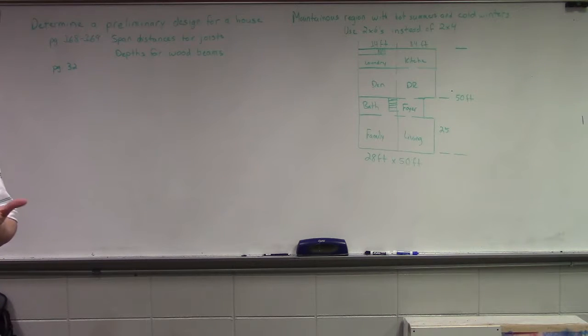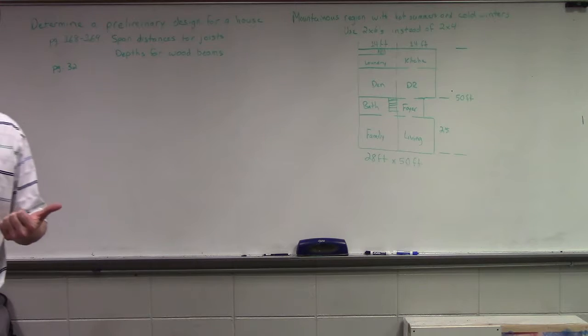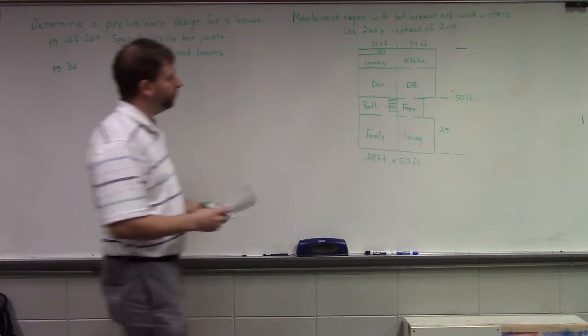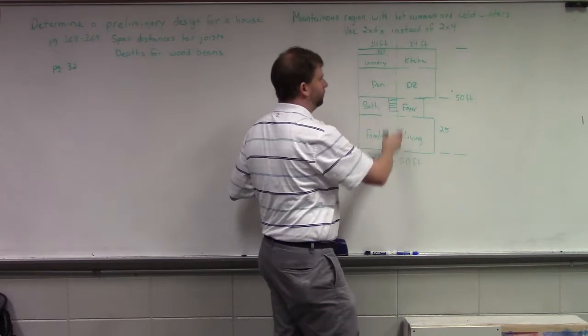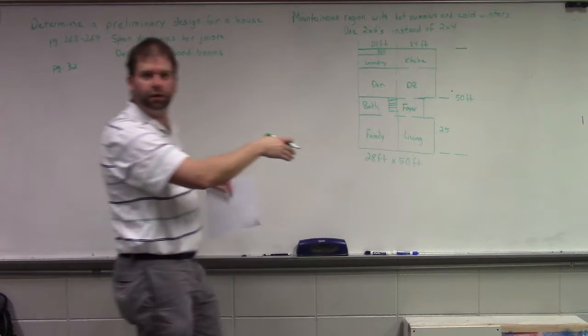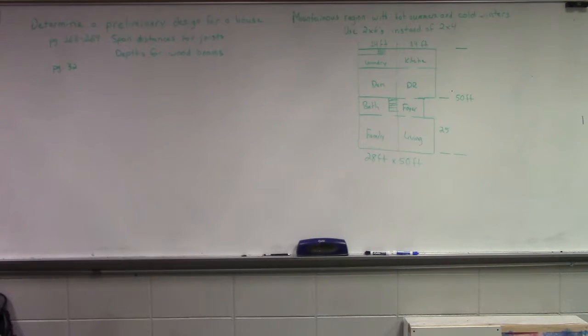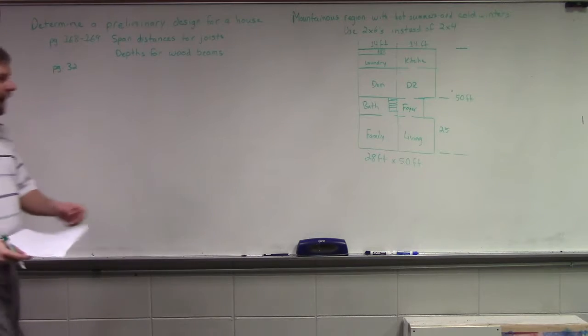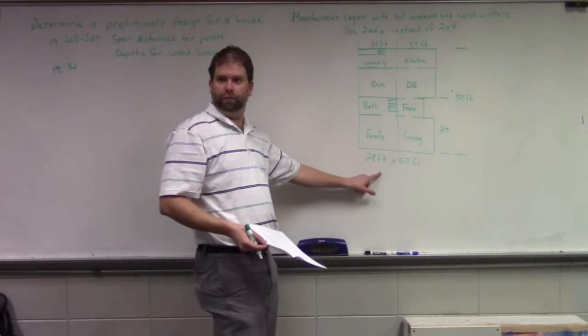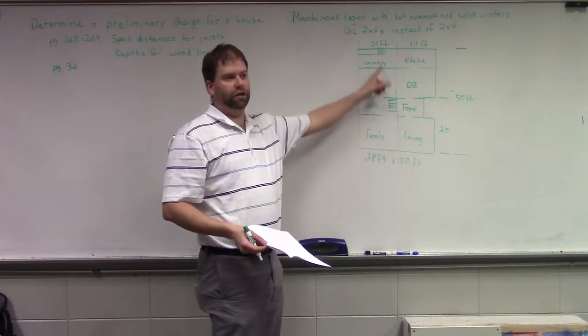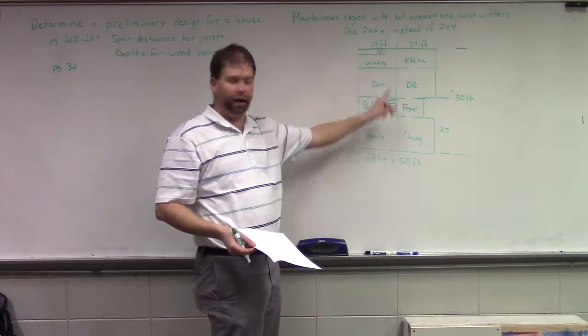Studs and sheathing. Our sheathing is going to act as our shear wall, okay? But we also have this section of the wall, which conveniently is running down the middle of the house. So we need to determine, do we have a sufficiently sized diaphragm? Are we going to need additional shear wall down that middle?